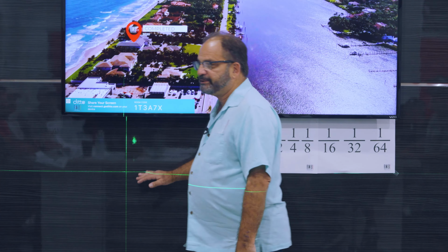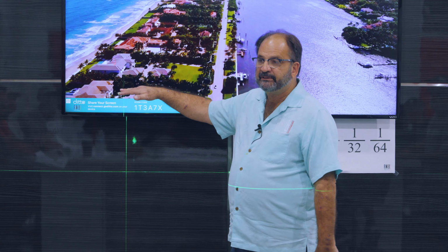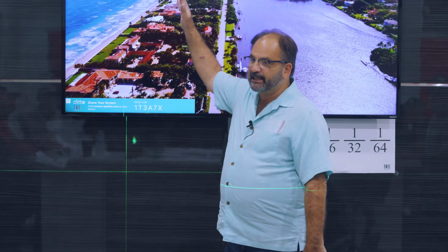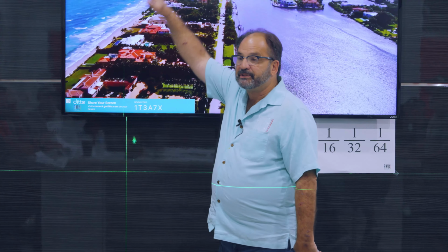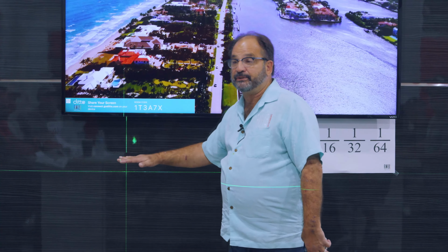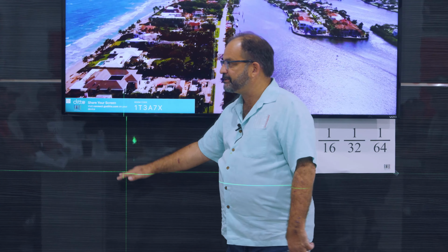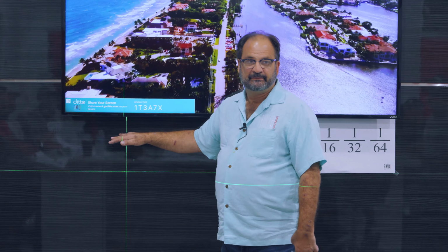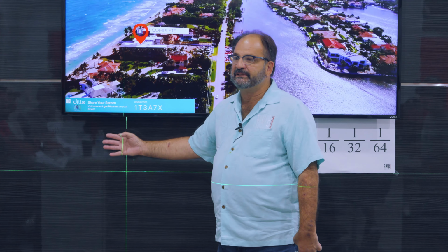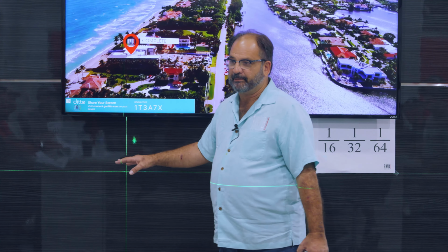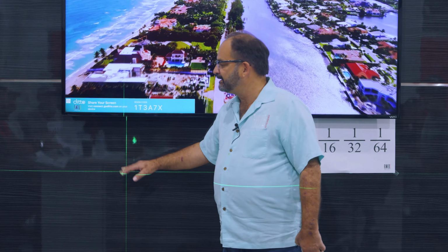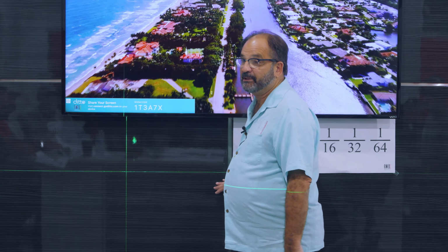You can measure down from here to the countertop. You can measure from here up to the bottom of the upper cabinets. You can measure from here up to your ceiling. And just like you're measuring from here up, the electrician is also measuring from here up. The guy doing the alarm system is measuring from here up. Everything that you're doing, everybody's measuring off the same line. Okay?